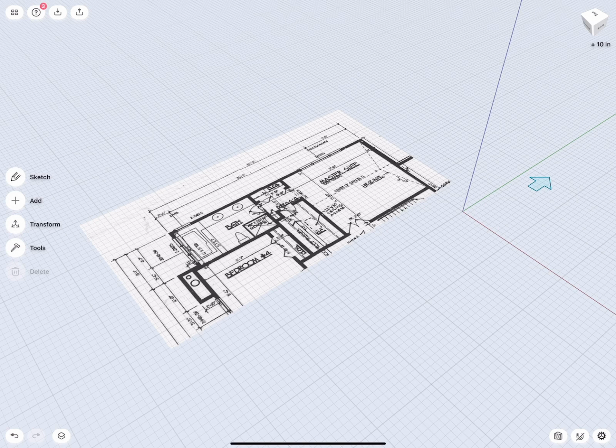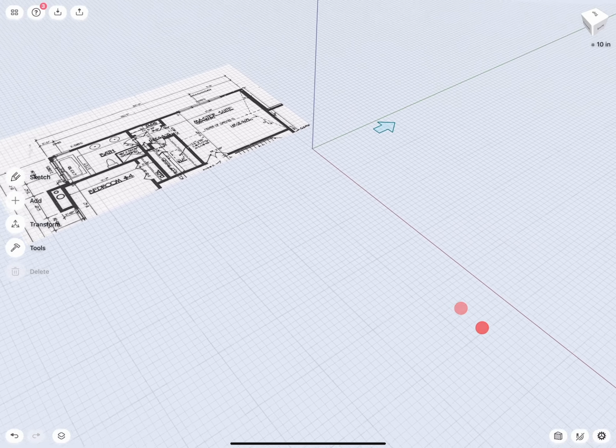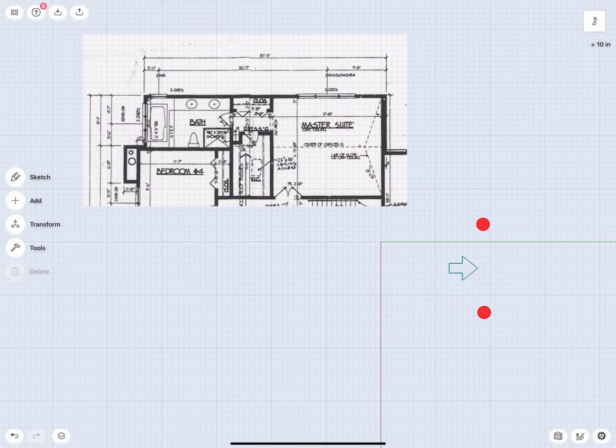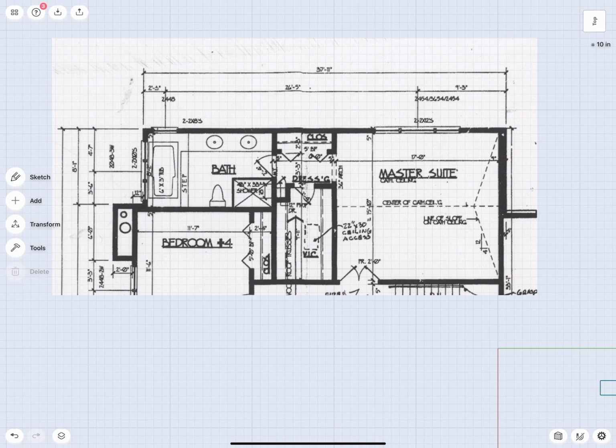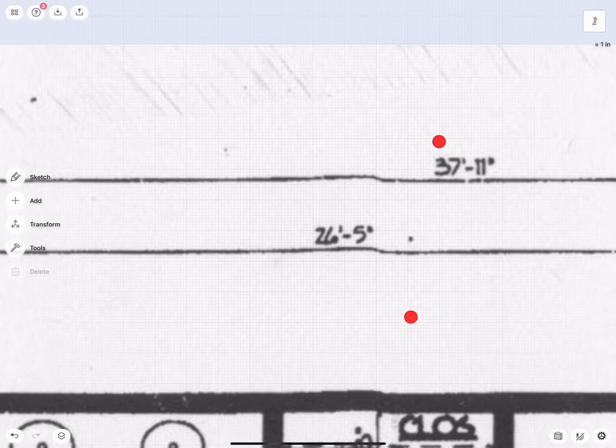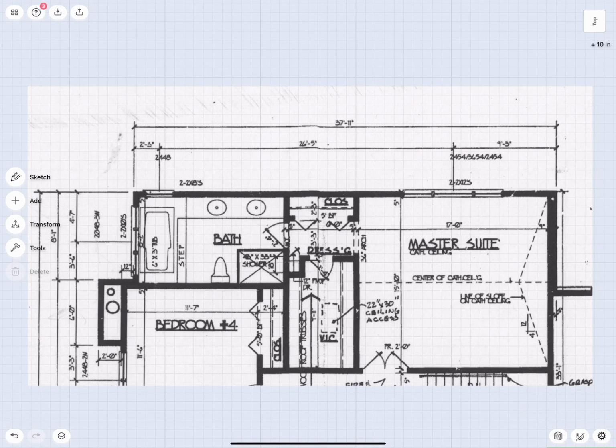Okay, so up front, for those who are in interior design architecture, now the arrow that basically navigates or directs the north position. And as you can see here, I have a scan of the property. At first sight, it looks pretty good, but if you look closely, you can start realizing that the scan has some serious issues. There are some interesting changes in the lines, and all that basically means that this construction document is actually distorted. So it's not really very good to use as an underlay.